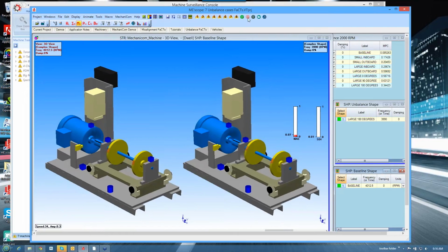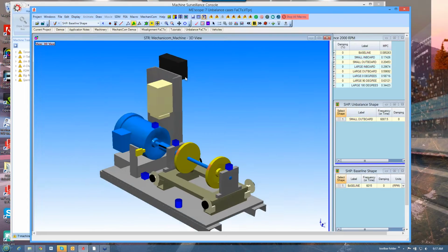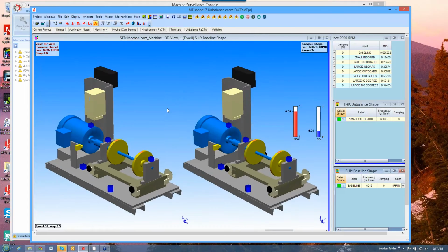Let's go to the third order. We got the third order in here, and we can kind of look. So this is kind of like modes of vibration. When you go to the higher frequencies and you upset the machine balance case, you excite different modes, and many times the high frequencies are very sensitive to any physical change. We know that if we look at structures and their stiffness or their mass changes. In this case, we have unbalanced forces. So this is really just forced vibration.